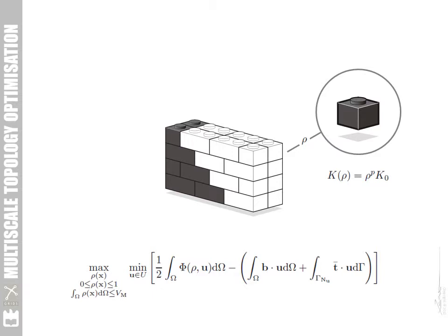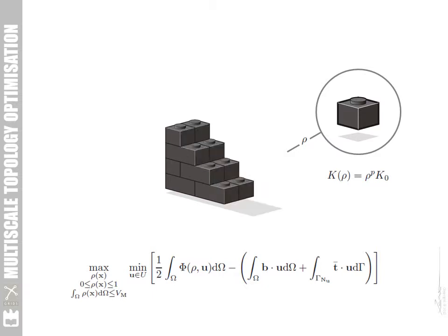We get to a point where we have material in the best regions and no material where it's not needed or where it's less needed. This becomes something more or less like what's represented, where we have material and void. We can get to the best solution possible, the best structure possible for a given objective, in this case, for better stiffness.